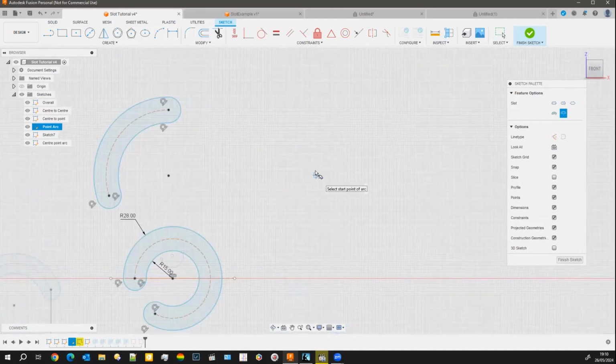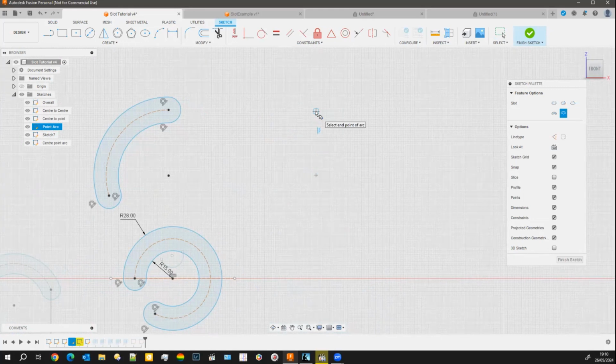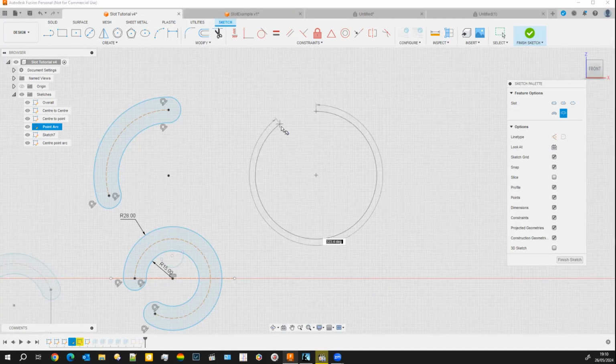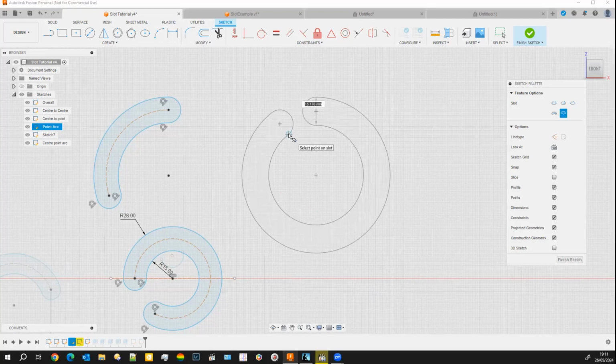Do that once again for you. Click your center point, go up the distance that you want the arc to be at from the center point, click left click again, pull it all around as far as you want. If you go all the way around, you'll just get a donut. Click there and then pull it out.